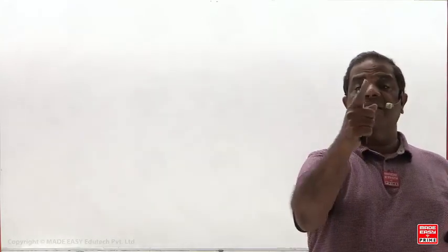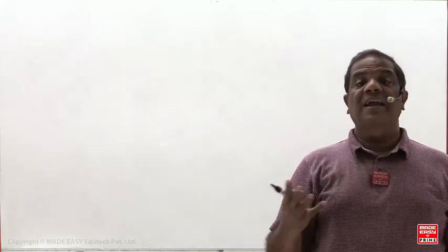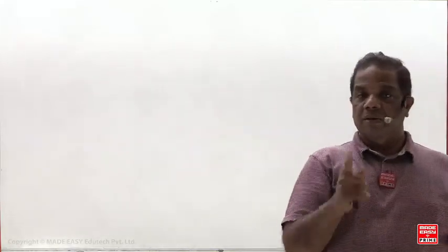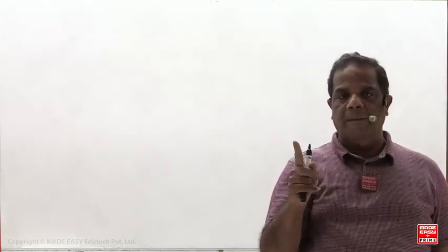So axial stress develops only on the X face. Y and Z face stress is zero. But oblique plane stresses are going to be there. This is what most students misunderstand.